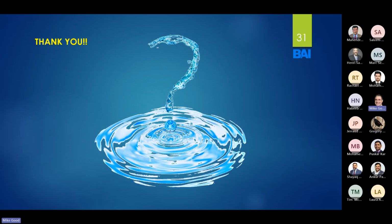I guess all that is to say, I'm sitting here, looking at my screen, and seeing lots of water resources engineers on this call, which is great. But it's all to say that hydraulic modeling is an imperfect science, because we're only as good as the information that we have to input. It relies heavily on geotechnical information. You might have one boring every 40 or 50 feet, so there's a lot of information that we're having to bridge the gap between these borings. We have to take it at face value and work with what's there.